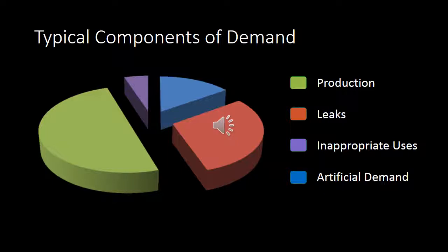Artificial demand is defined as excess volume of air consumed by unregulated end users as a result of supplying higher pressure than necessary for the point of use applications. Equipment fed through a pressure flow controller or through regulators will only use air at the regulated pressure. Equipment connected to part of the distribution system that does not have specific pressure or flow control will use air at whatever pressure prevails at the time.